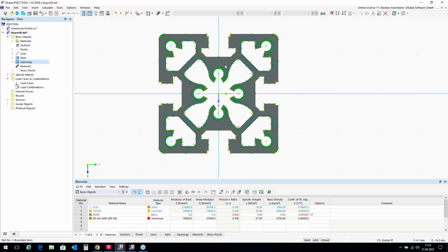So now you can see, if you had said, okay, I want the thin-walled analysis with a cross-section classification of elements, it's quite hard to do that because I have quite an irregular cross-section here. I could say this could be an element here, but the next ones would be quite hard to define. So this example is very useful for using the finite element calculation as a method here.